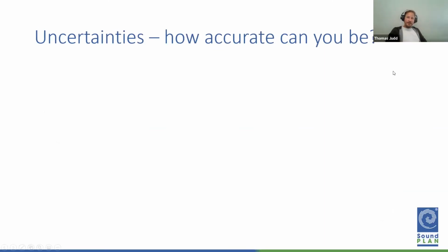Tied into all this, of course, is the issue of uncertainty in your results, because you saw in the case of that office, even after the results had largely converged, they were fluctuating around a bit. The question is, are those little fluctuations significant? Do you have to worry about them? And the truth is, you do not have to worry about them if they're only moving within your overall uncertainty. And for this reason, to understand what sort of geometrical detail level you need, you need to understand what the uncertainties in your results are. And I confess, I have to beg your indulgence.